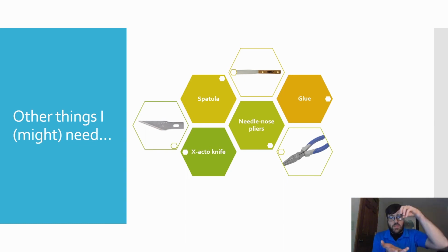A lot of times your print is going to be stuck to that print bed. If it's a taller print and it's pretty solid, you may be able to just kind of crack it off. But if it's something that's a little more delicate, if it's a print that's a little more complex, you're going to want to use a spatula to get underneath. One thing sometimes we use at the library are old discarded gym membership cards or things like that. You can kind of slide underneath and get started. These prints do get really stuck to the print beds a lot of times.